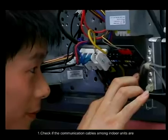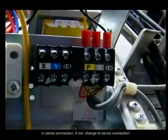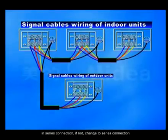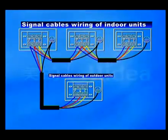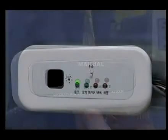1. Check if the communication cables among indoor units are in series connection. If not, change to series connection. 2. Check if addresses of indoor units are repeated.